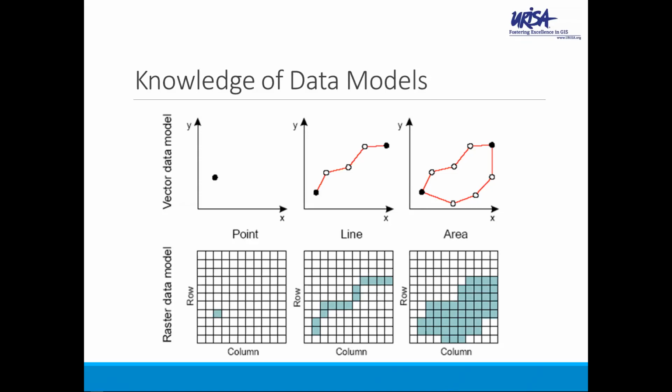The other types of data models that you'll want to get brushed up on include triangular irregular networks, network models, so geometric networks versus, say, road networks, and the object-oriented model, and the advantages or disadvantages of the ways of representing the various types of spatial data. There are times when it may make more sense to represent something as a raster than as a vector.